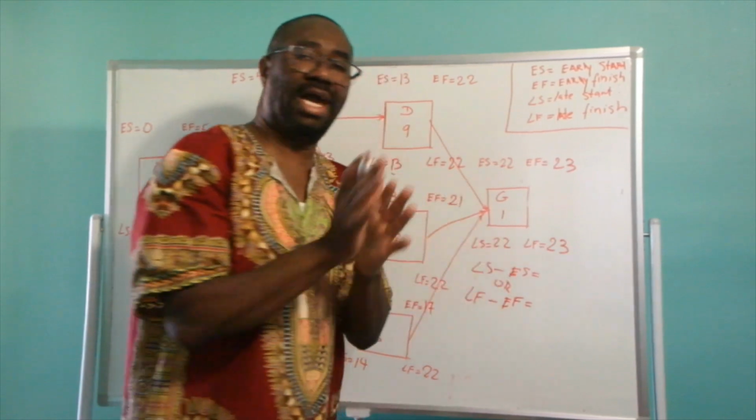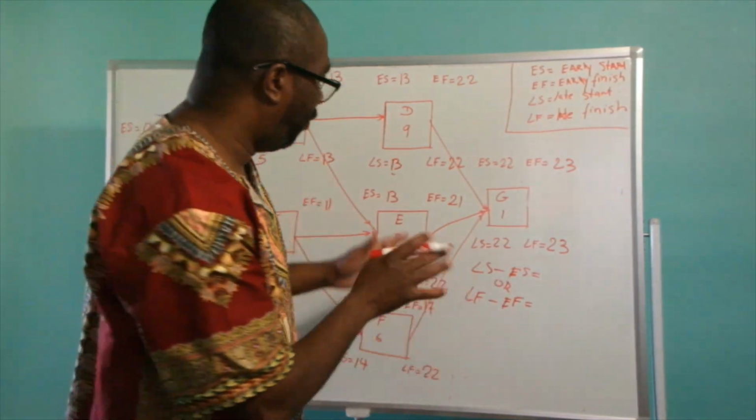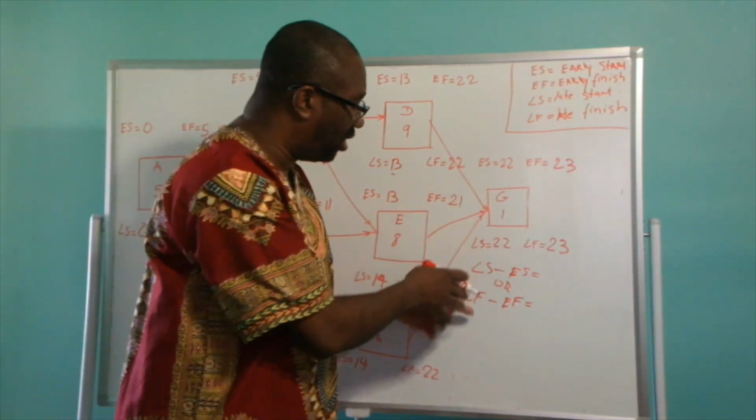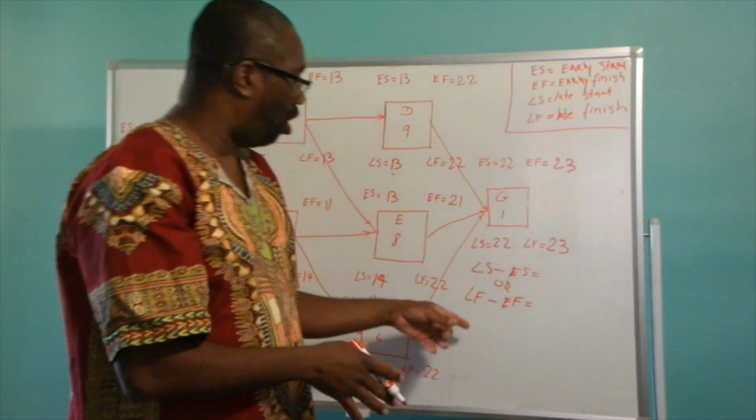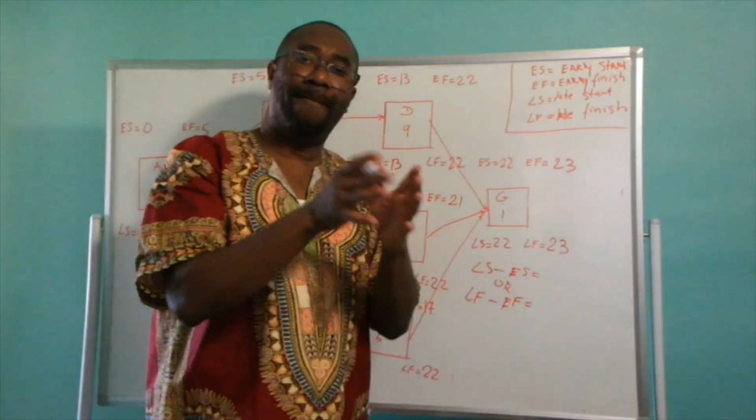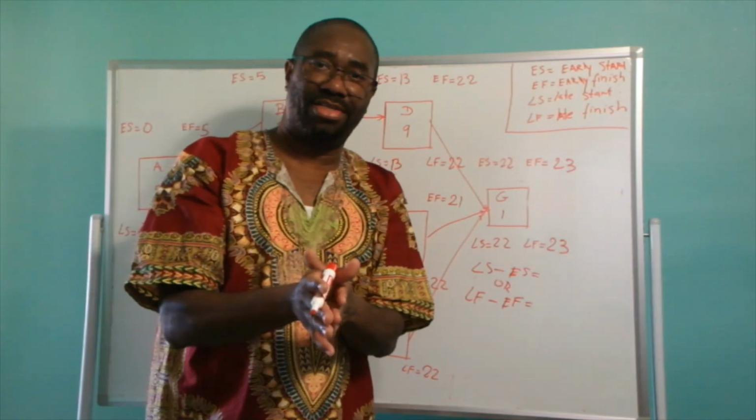So that's how you calculate your float. Your float is your late start minus your early start, or your late finish minus your early finish.